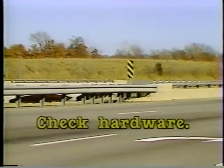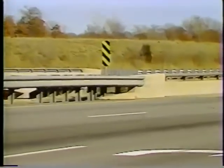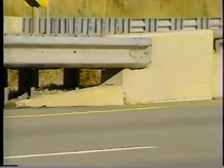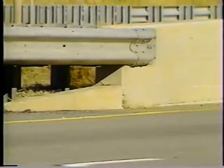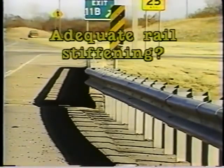Transition sections of W-beam strong post systems are usually easy to inspect. Make sure that all connections are correctly installed. Transition section bolts tend to loosen where guardrail and bridge railings join. Make certain they're tight. Check to see that the section is properly stiffened.